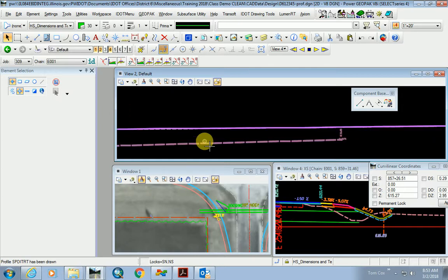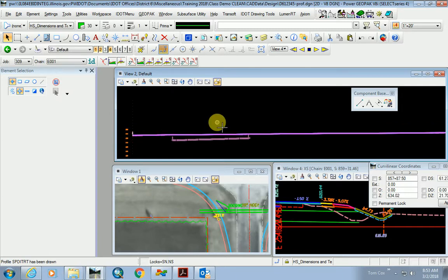This is one of them that you'd find in there. This is just IDOT's way of defining a right special ditch. Everything has its own symbology. But fortunately, you don't have to memorize any of that sort of thing because we just went to the DNC manager. Somebody had already taken care of that for us. We just said, hey, this is right ditch. And like everything else, it said this is the symbology that you'd use for the right special ditch.